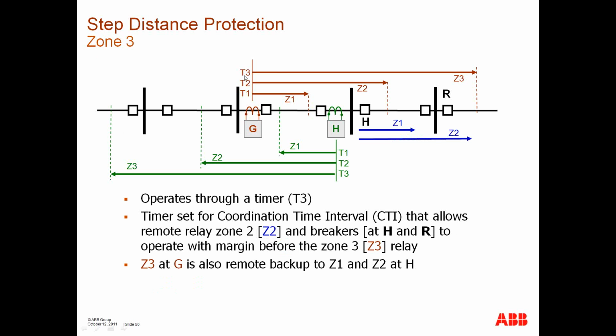Zone 3 operates through another timer, and again what you want to do is allow both Zone 1 and Zone 2 time to operate before this operates.